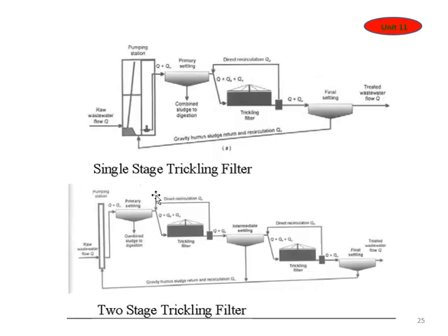This is the picture of the single stage. For example, this is the wastewater coming from the primary treatment, then it will go to the trickling filter. After the trickling filter it will go to the sedimentation tank. This is one unit, so this is a single stage. If you add one more unit, then it is called a two stage. If you add more and more, it will become multi-stage trickling filter. Depending on how much treatment you want to do, you can add units based on the quality of the effluent you need.